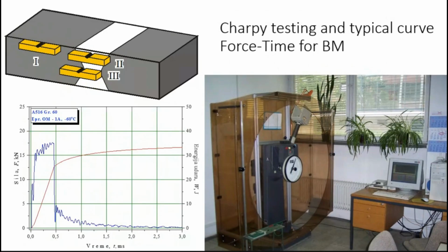What we get from this instrumented pendulum is a force versus time diagram, and using it, we can separate the energy to initiate a crack, which is practically the area up to this point, and then the energy for crack growth, which is the remaining area. In this case, you can see that energy for crack initiation is much larger than energy for crack propagation.